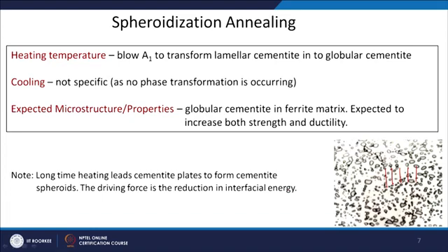So, for the same volume of, let us say, pearlitic cementite, if I have this kind of elongated morphology, you will see that the surface area is going to be large here, and for a given volume the smallest surface area is always going to be there for a spherical shape. This we already know from geometry: for any given volume, a spherical shape is going to have the minimum surface area. That is why we do this spheroidization.